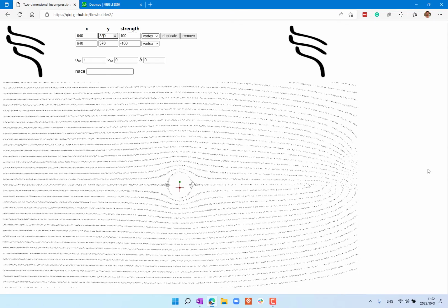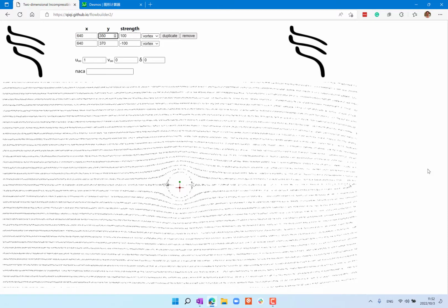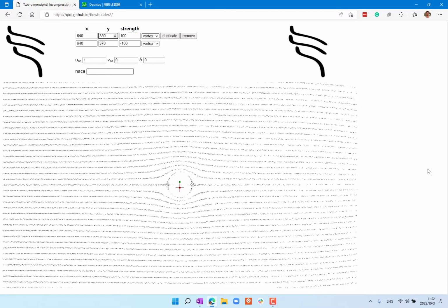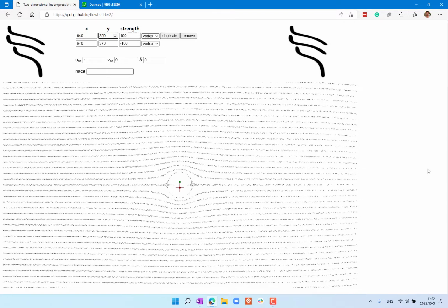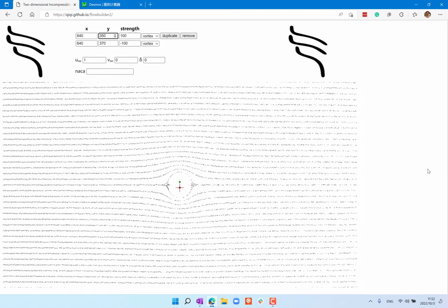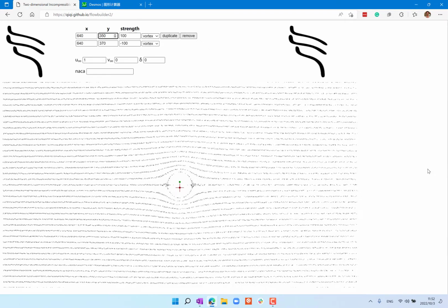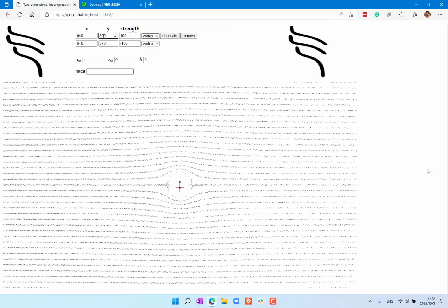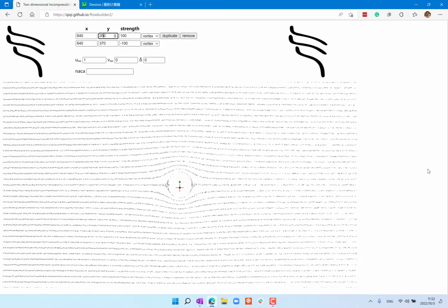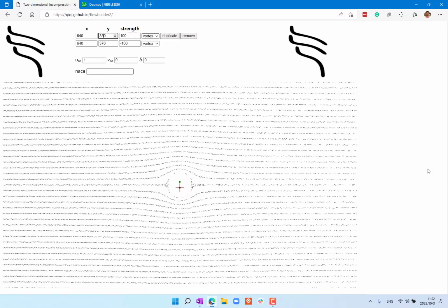Yeah, it's like a cylinder in the middle, right? So that is starting to look like the flow around a solid object that's symmetric. All right. So basically we can play with all kinds of stuff, and here you can see the stagnation point, right? Pressure is highest there, and pressure is lowest on the two sides, up and down, because the stream tubes are the narrowest.